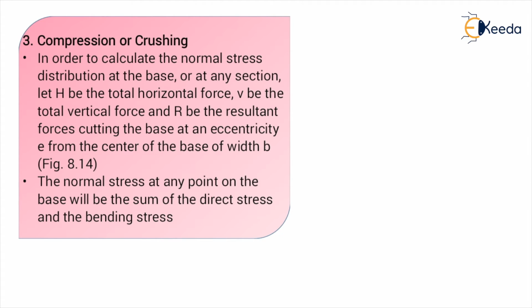The gravity dam will fail, or the mode of failure will be in a compression or crushing zone also. So what exactly is this? See, in order to calculate the normal stress distribution at the base or at any section, we have to know the total horizontal force and the total vertical force.